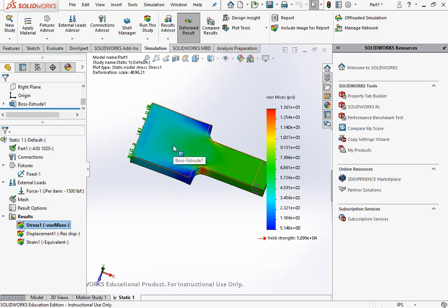And there's actually, I don't know if this version of SolidWorks has geometry optimization in it or not, but once you get past the general design, there are procedures where you can let the computer automatically start chopping away pieces and creating web-like structures where the material is needed. Now, to make those structures, you have to use some additive manufacturing process. Normally, you're not going to create that on a subtractive process like a mill or a lathe, but there are other things you could do.